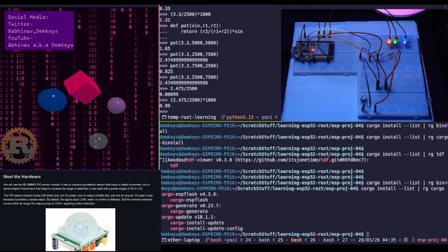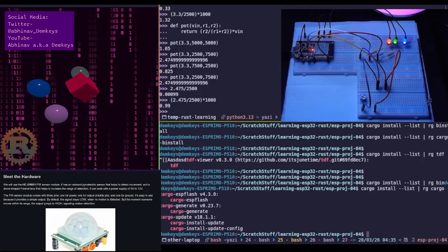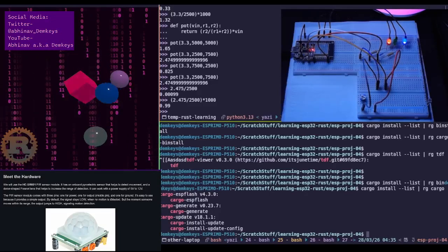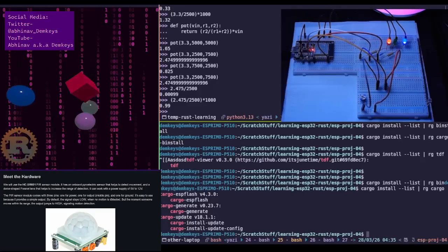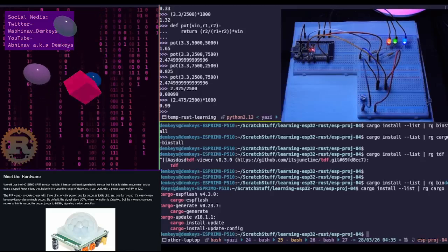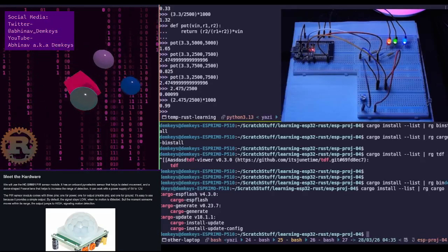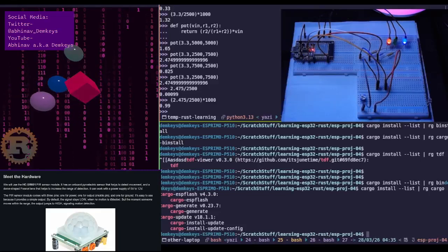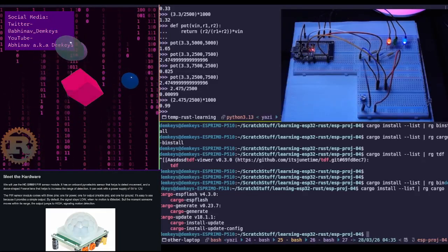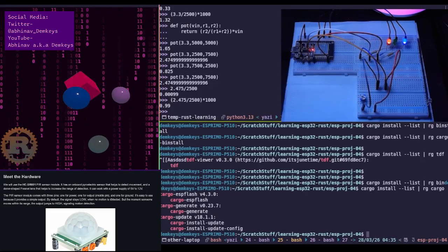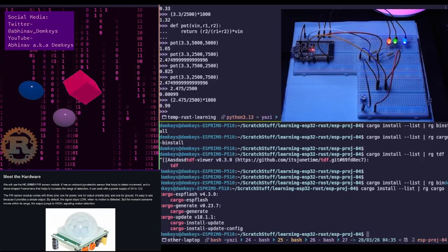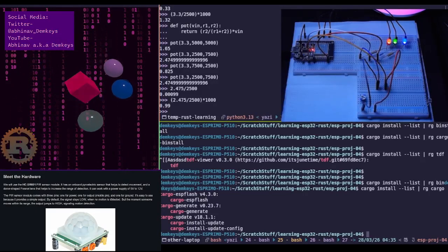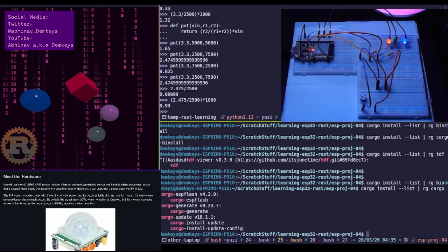What is this used for exactly? Okay, it says we will use the PIR sensor module. It has an onboard pyroelectric sensor that helps to detect movement, and a dome-shaped Fresnel lens that helps to increase the range of detection. It can work with a power supply of 5 volts to 12 volts. Oh, 5 volts. So I'm going to need to plug VIN into it, not 3.3 volts.